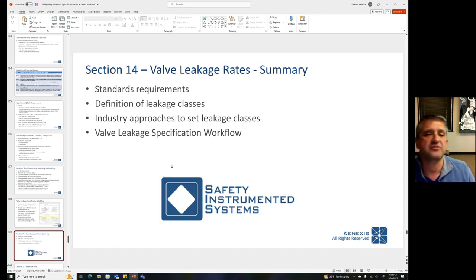What did we talk about? We talked about standards requirements. What does 61511 say about leakage rates? Most of it came from clause 10.3 SRS. We talked about where in external standards from ANSI, from API, from IEC, that these leakage classes are defined, and we kind of made the recommendation to go with class 1 through class 6 as opposed to trying to use a term like TSO, which really has kind of loose and conflicting definitions in a lot of places.